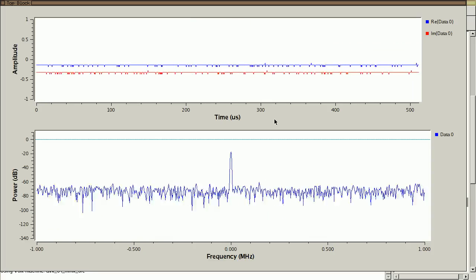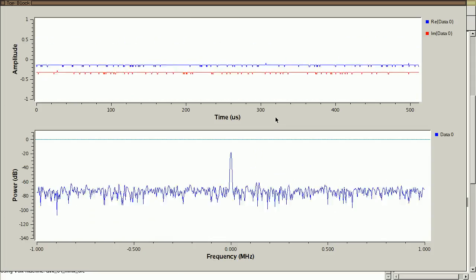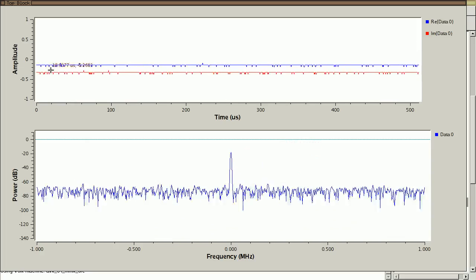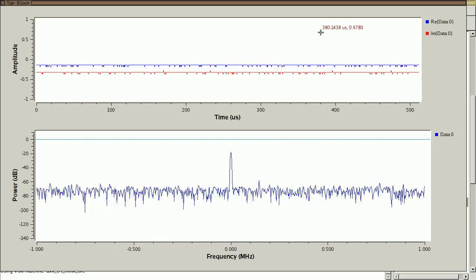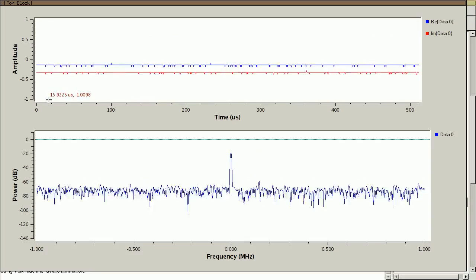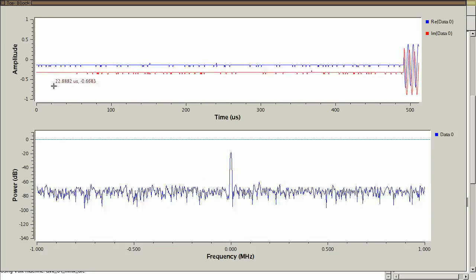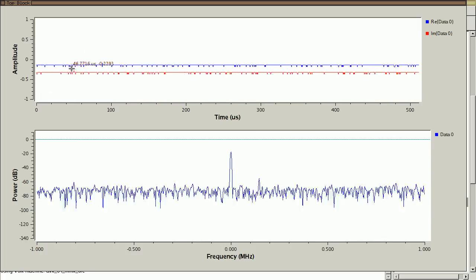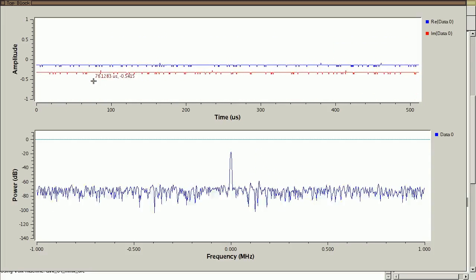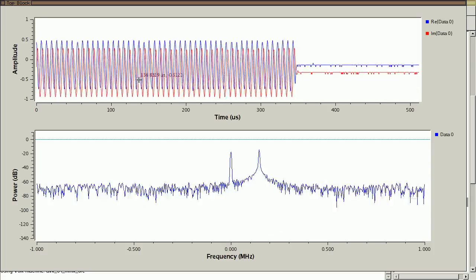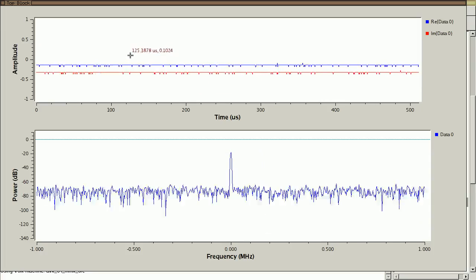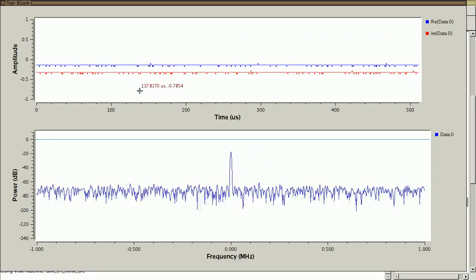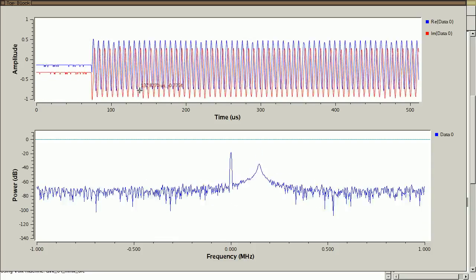Things look pretty much the same, except notice that in the FFT sink, everything has shifted up a bit, and in our scope plot we can see that the sample values are in fact extending from about 0.5 to -1. If we were to remove the DC offset or just shift it up a little bit, we could even gain a little bit more dynamic range, but not a whole lot. Now we're using most of the full scale that is available to us. And I want you to realize what happens here.